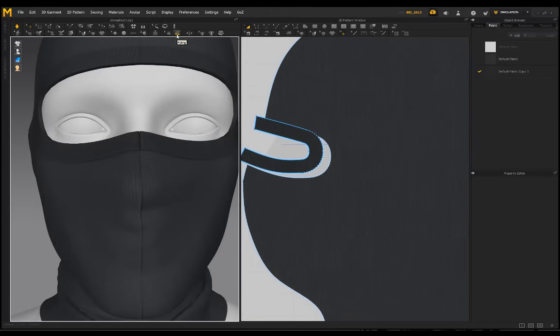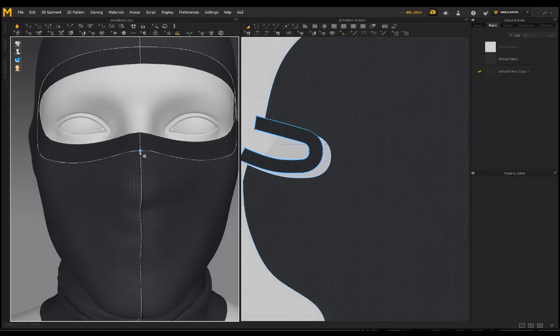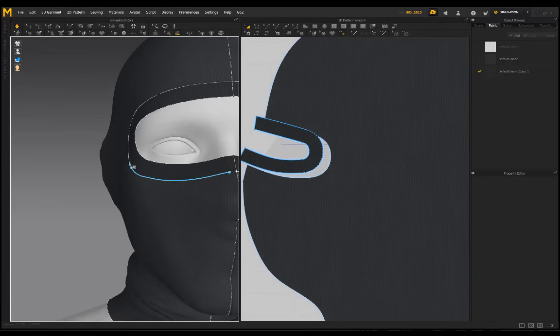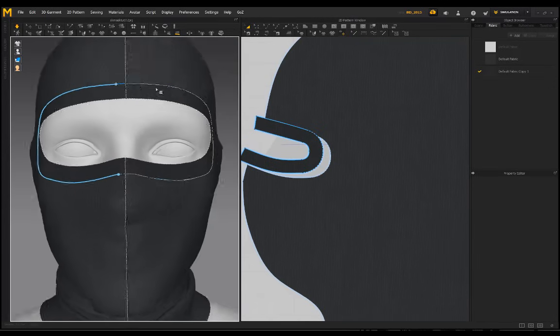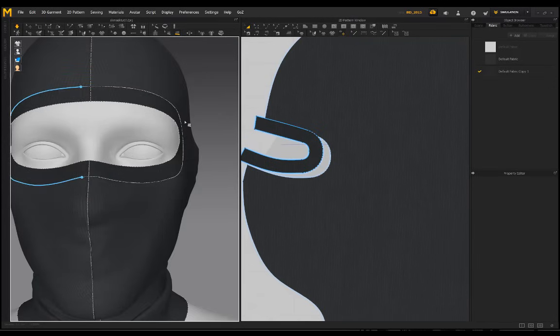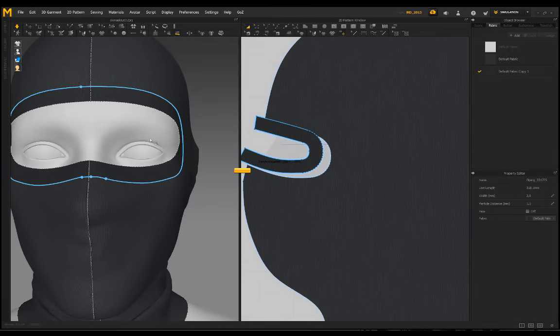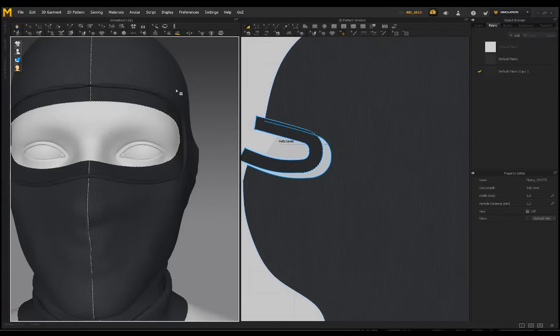Okay, so you want to go over here to piping. It's going to bring up all these white dots. So I'm going to start placing a point over there and go around to there. Left click to put another point, come back around, put a point there, a point there, and then connect it with that one, and it's going to create piping for us. So just let that synchronize, give it some time, and now your piping can be its own color as well.